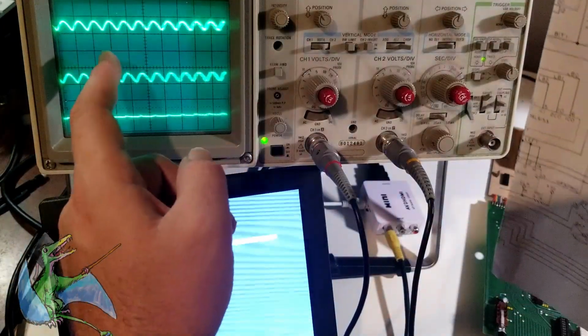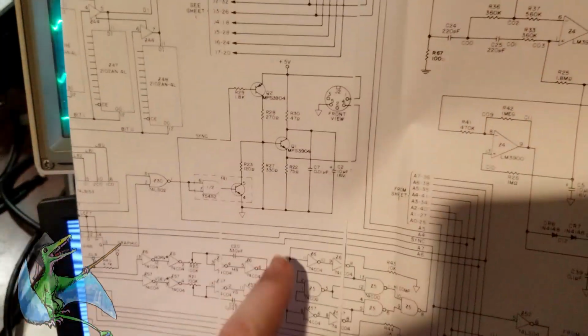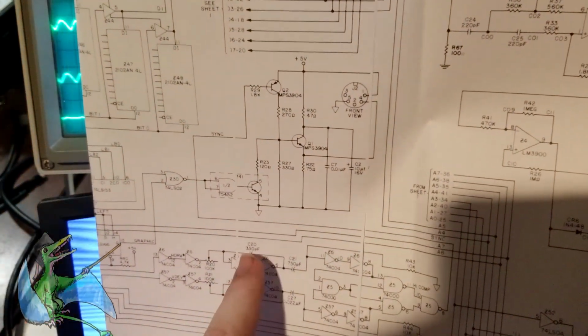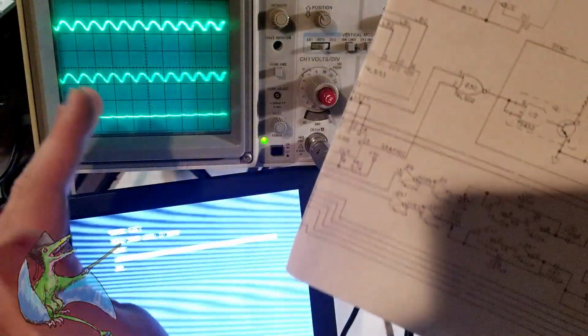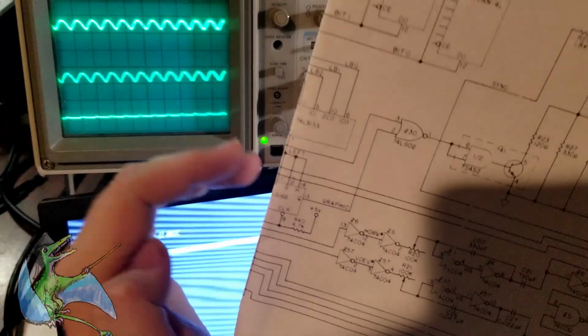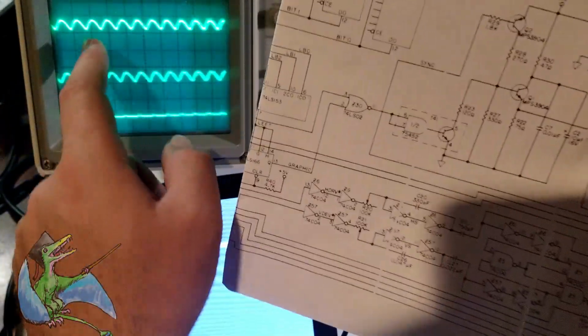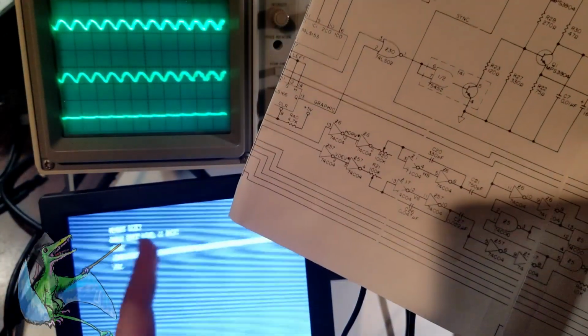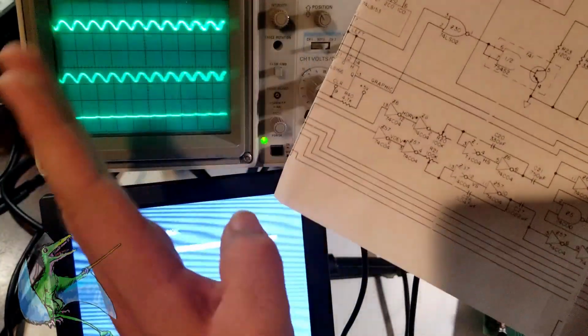The frequency of this is almost perfect to cause this capacitor to charge at varying rates, so we end up with longer and shorter delays basically every scan line. And because it's a fraction of the line length, that explains why it can look like a rocking pattern.